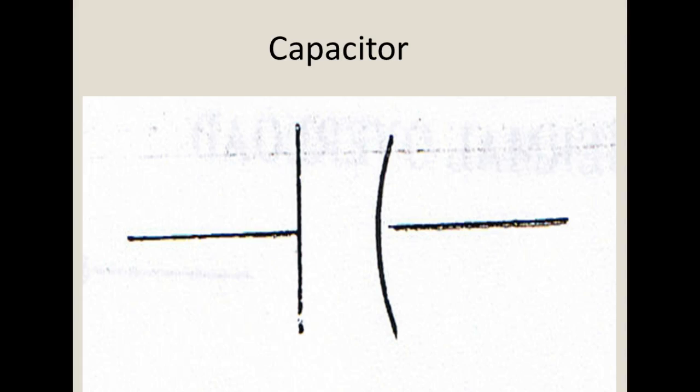And so one of the methods is what we call a shaded pole. These are considered poles. This is a positive pole right now, right? And that's a negative pole. See this clip over here? I'll pass this around. See this copper conductor? That's a shaded pole. Now, what we do here, and this is a very cheap motor to manufacture, but it's not energy efficient, and it doesn't have much torque.